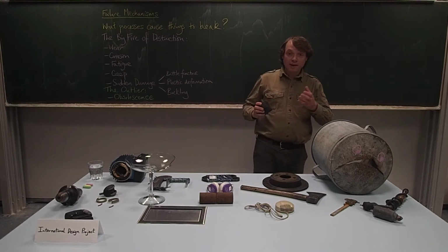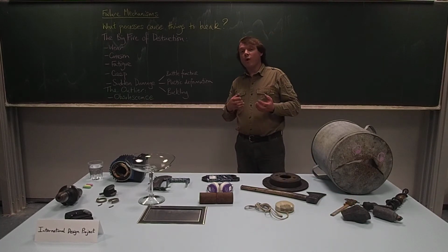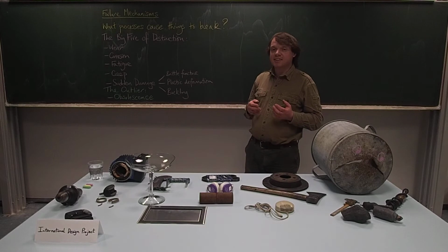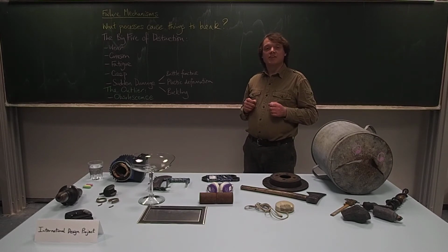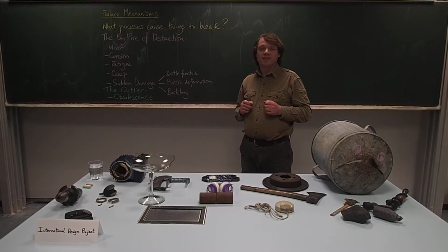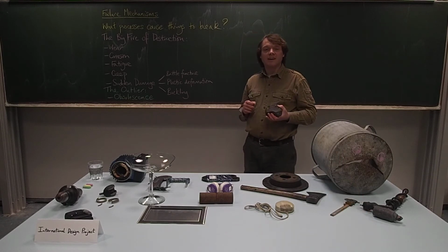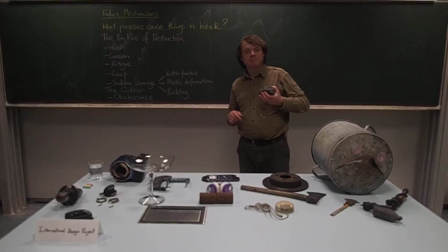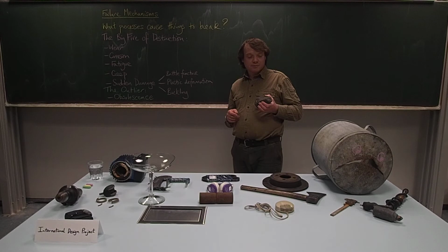So you have your pure metal, and then when it gets hot or wet, it has a tendency to create an oxide, because energy is released by the reaction going in the opposite direction. And most of the oxides are much, much weaker than the pure metals. Here you see this piece of magnetite. You wouldn't be able to make a thin component out of it that was a millimeter thick or something like that. It would be so brittle as to be useless.